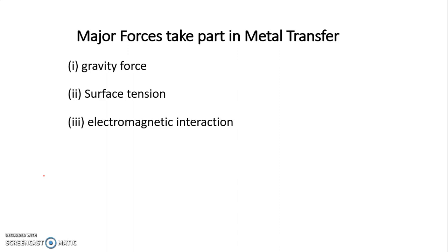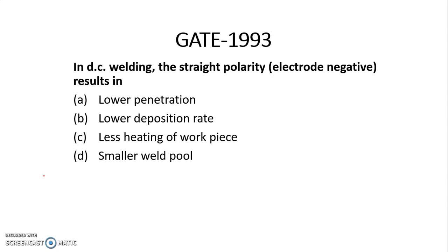The major forces that take part in the metal transfer: first is gravity force, second is surface tension, third is electromagnetic interaction, and fourth is hydrodynamic action of plasma. With the help of these four forces, the metal transfer takes place.